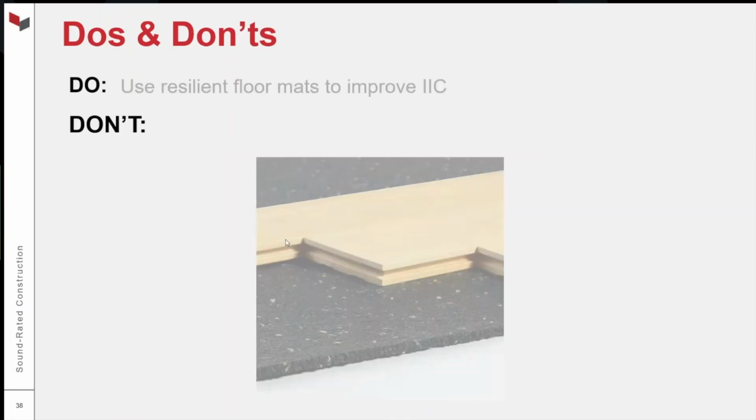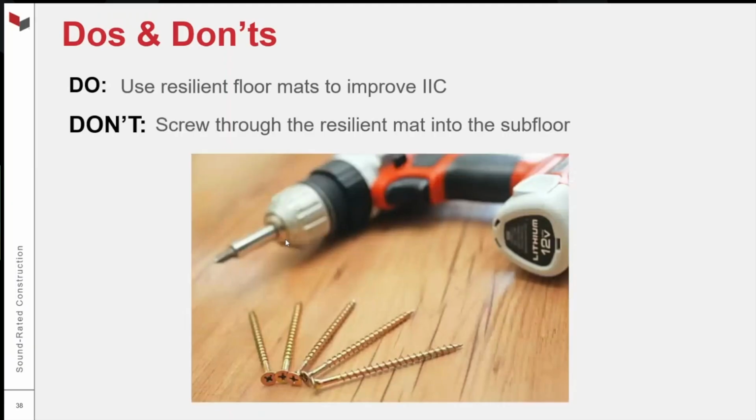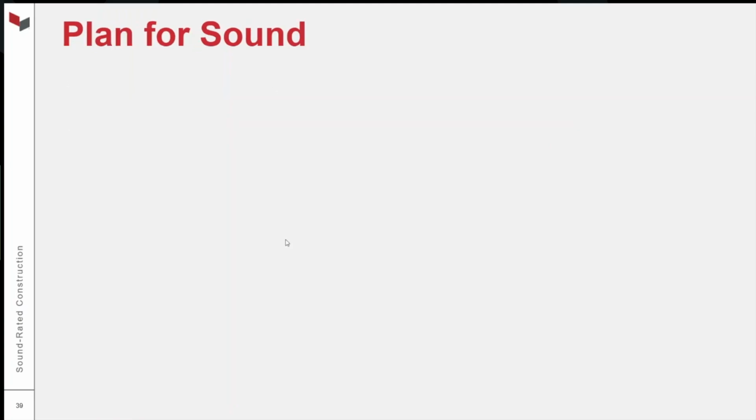Lastly here, do use resilient floor mats to improve IIC, but don't screw through the mat into the subfloor. If you screw your finished floor or if you staple the mat, you're just inviting, just like I showed the short circuits for resilient channels, this is kind of short circuiting your sound mat. You're gonna start to hurt the IIC benefit that you would otherwise get with your resilient flooring materials. Try to avoid that. And lastly, plan for sound.